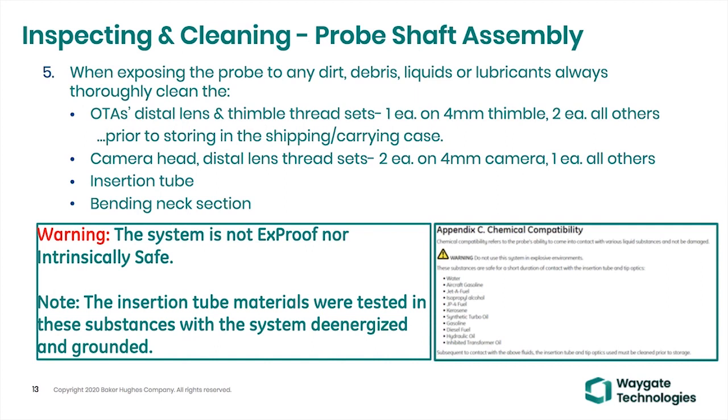And when we're talking about cleaning this, you're going to be using alcohol and water because you may have gotten some products on there. The question often comes up, well, can I use this in oil? Can I use this in various products? The first caveat I want to make sure everybody is excessively clear on is this system is not explosion proof and it is not intrinsically safe.